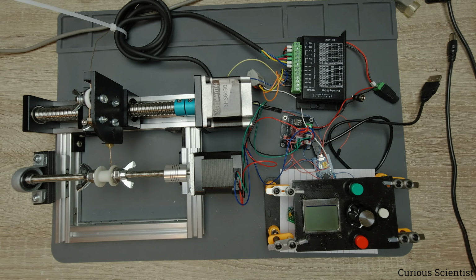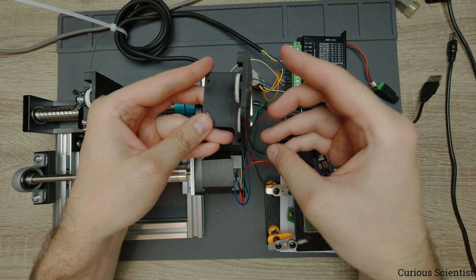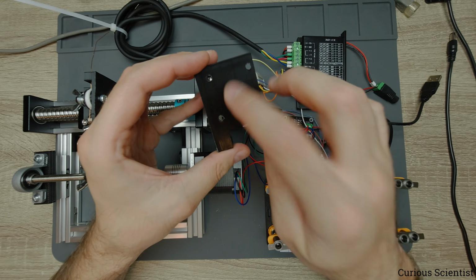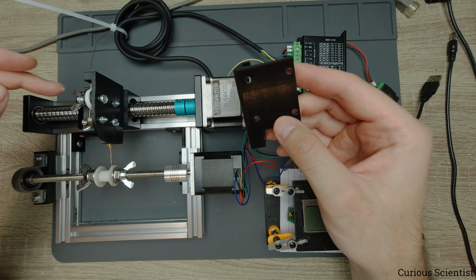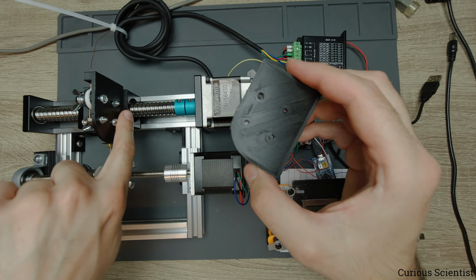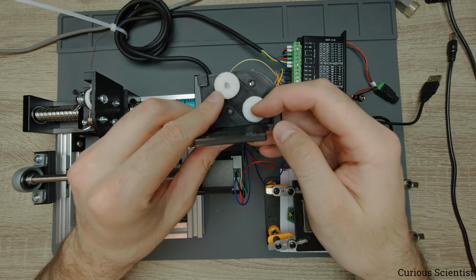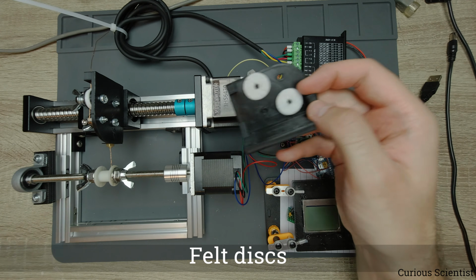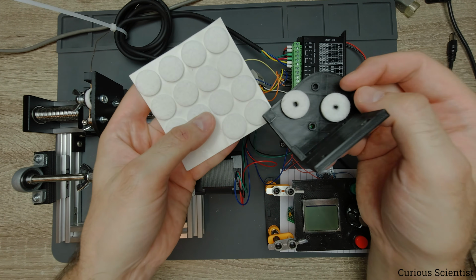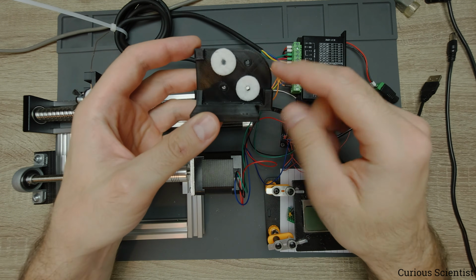Coming back to the feeder part, I actually have another piece here. What you see there is sitting like this. This bottom part is connected to the block on this ball screw, and then this other back plate holds four different things. You can see these two white felt discs. These are regular felt discs which you can buy for furniture, for example for the legs of chairs or tables. I put them here to introduce some kind of friction.